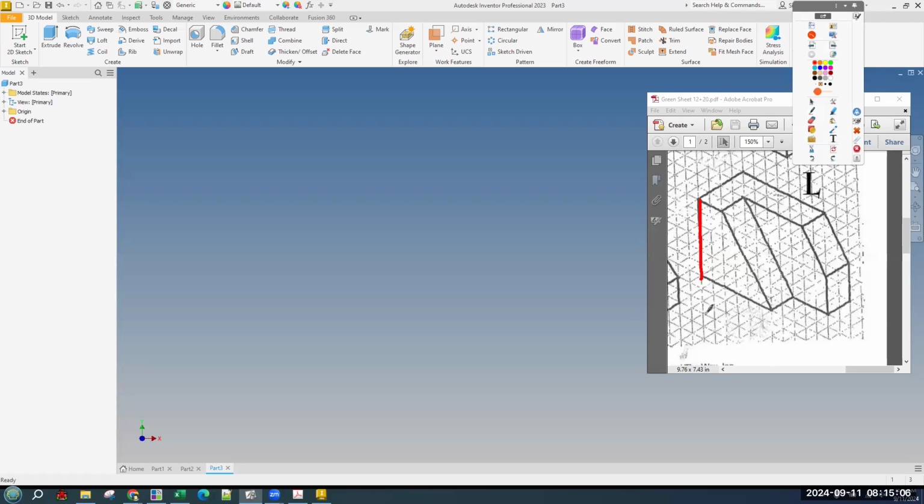And it's 6 tall on the front or on the left, whichever. It is 1, 2, 3, 4, 5, 6, 7, 8, 9. It's 9 wide, and its depth is 4. So we're going to go a rectangle 9 by 6 and extruded 4, and then we'll check back in with the shape.